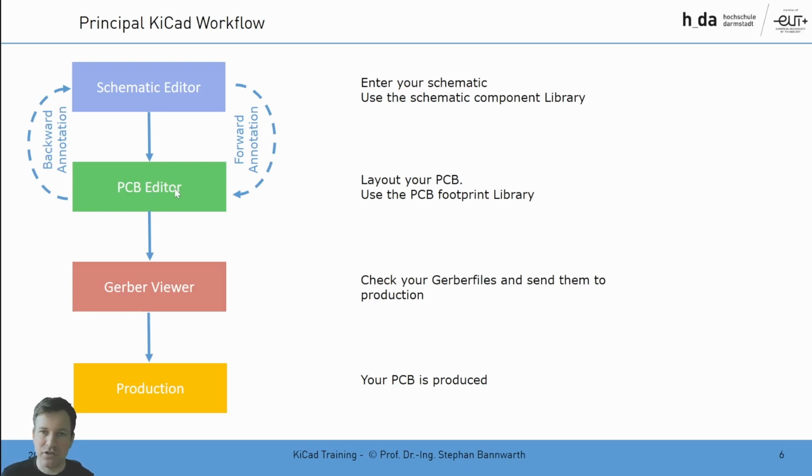Once this is finished, you have your representation of your PCB in your PCB program, and you see the different copper layers where you have connections between the different layers and where you have drawn the traces for your signals or for your power planes, for example.